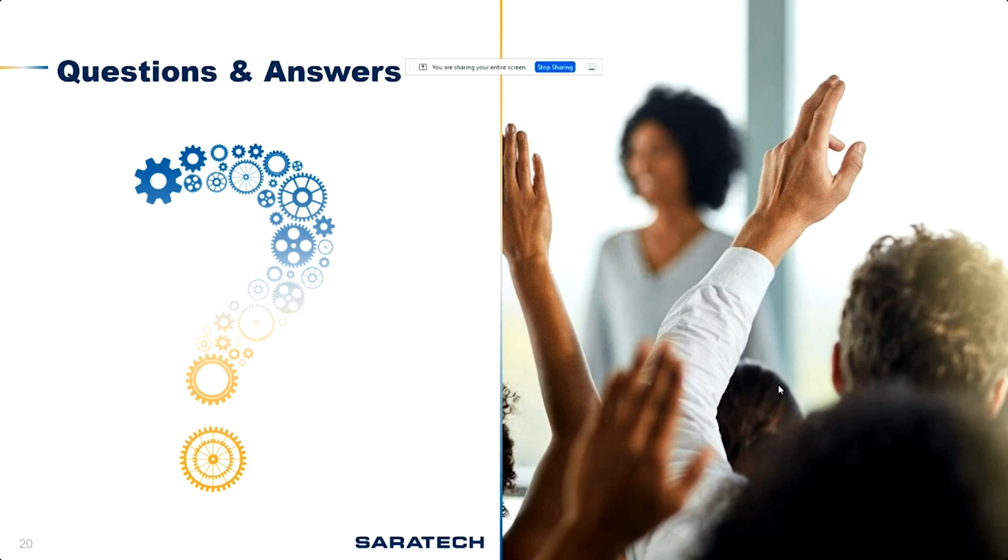So the 4 hours that it took you to develop that draft does nothing for us other than to view it. Now we just redirect that 4 hours into PMI data, and that PMI data reduced our CAM programming and/or CMM programming by 80%. So it's just a matter of reallocation of effort. Unless it's absolutely corrupted data coming in for the model, or something of that nature where a PMI wasn't able to attach to an entity, there wouldn't be any type of remodeling.